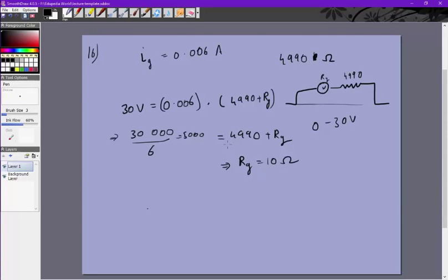Next you are converting it into an ammeter, and when you convert it into an ammeter, you have your galvanometer and you put a very small resistance in parallel with that and connect it in series with the circuit. The reason is, if there is a very small resistance, most of the current will go through that and only a tiny fraction will go through the actual galvanometer, because only a tiny current gives the maximum deflection. So we've scaled an ammeter up.